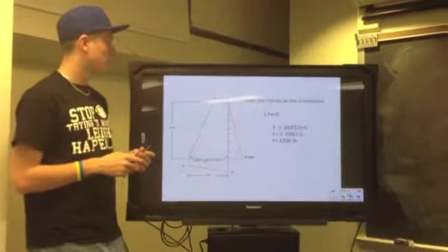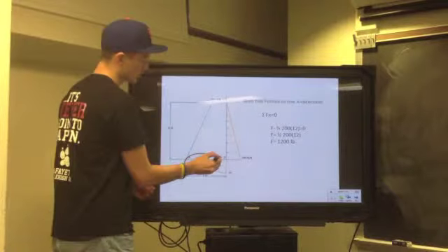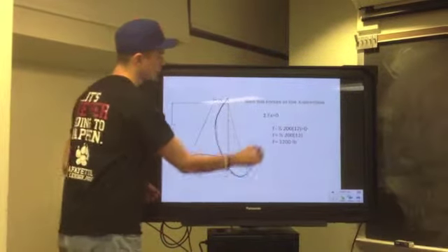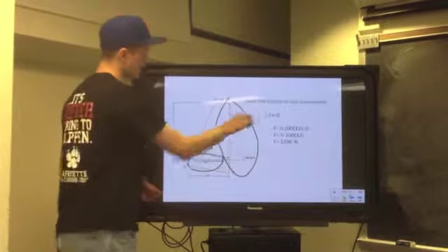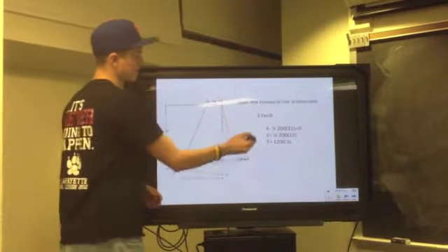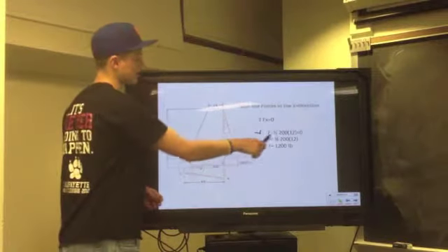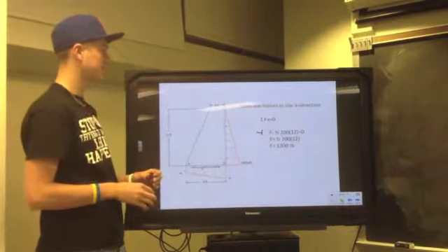Alright, so to begin our problem, we're going to sum the forces in the x direction. So that's taking the frictional force given here and equating it to the distributed load on the right side. So the frictional force is acting in the positive x direction, so that's why the F has a positive. And the distributed load is acting in the negative direction, indicated by the negative sign.